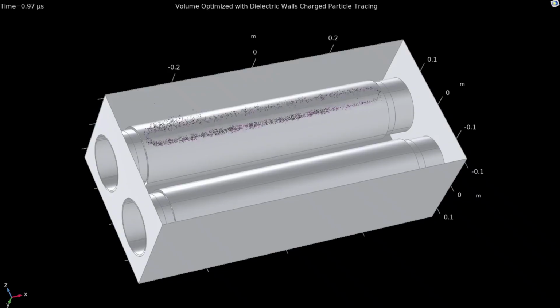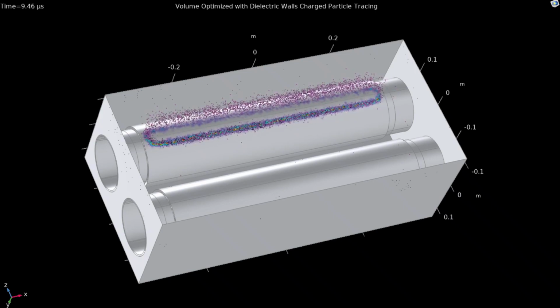So as we insert our electrons into the system, you can see on the outside racetrack, as those electrons come around the turnaround, how far apart they're moving as compared to the inside racetrack where they're really tight and close together. So that's going to spread out the ion creation on the outside racetrack and keep it very concentrated on the inside racetrack. You can also see that for the 10 microseconds that we just ran here, without changing anything but the chamber geometry, same pressure and everything, our plasma intensity did not become nearly as large as the other models.